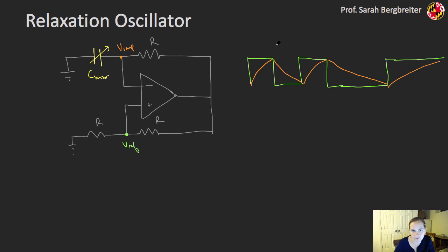So if I say the sensor was at some capacitance here, C1, and some capacitance here, C2, with this slower frequency, let's call this F2 and F1. F2 is smaller than F1, or similarly T2, the period of this, is larger than the period of 1, is going to imply that my capacitance C2 is greater than capacitance C1. Because once again, this is based on a time constant. It's just a slightly different configuration than trying to measure tau explicitly.